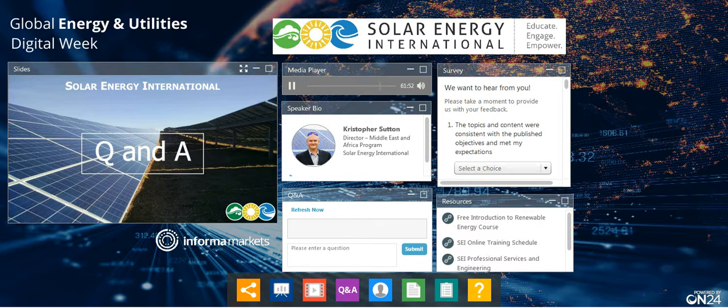So to use residential power in that situation where you can't sell to the grid, you're probably looking at a battery-based grid-connected system where you can use the solar whenever you have sun, and use the battery depending on whether the utility comes on or off.